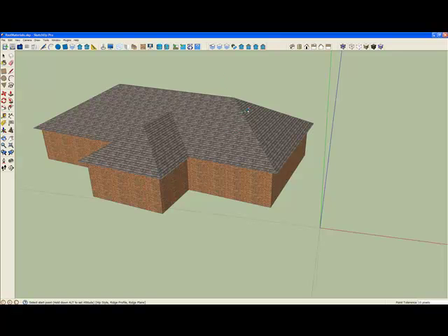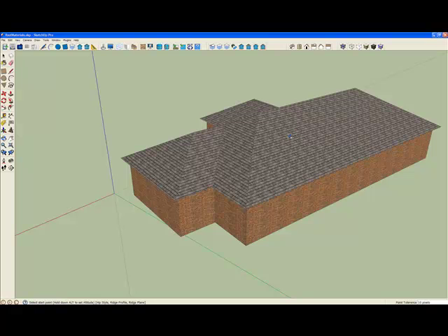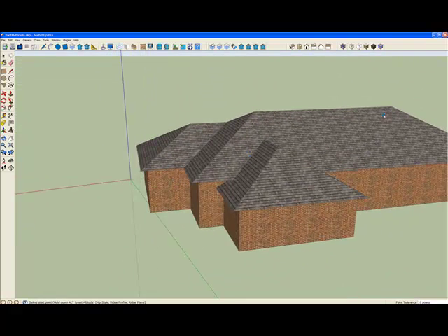Now when I'm working out at the edge, when I select the first point, it'll tell me when it's perpendicular to this roof line or the other roof line. And in this case, once again, I'll snap to the eave and they'll make the edges line up. But of course, it may be the case that you don't want the eaves to match, so you can start on the roof face, and in this case, hold down the control key so it won't snap to the ridges being the same. And now it'll create a multi-level roof, or if you were doing something like a dormer.